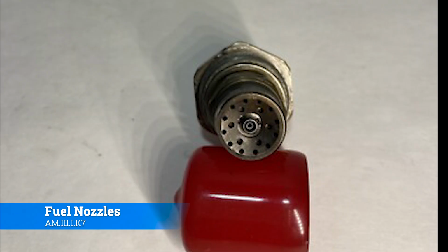The nozzle you're looking at right now came out of an Allison 250, or a Rolls Royce, depending on what era of engine you're looking at. But it's the same engine that goes in the MD500, the Bell 206s, 407s, and so forth. On that nozzle you can see the little ports in it. You're looking at the spray side directly at your face, and away from you is the side where the fuel line hooks up.